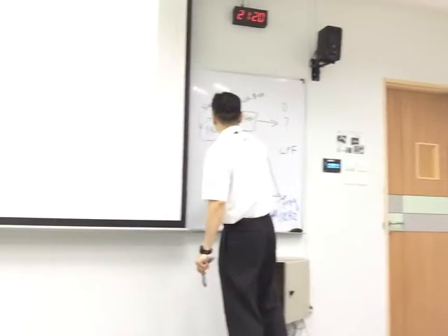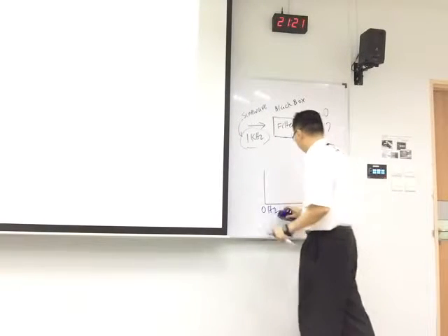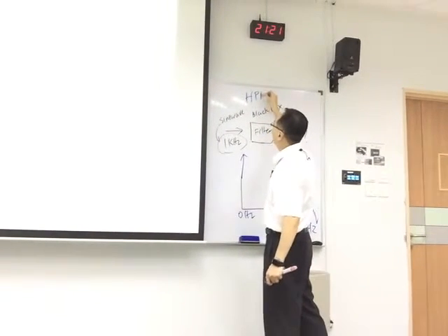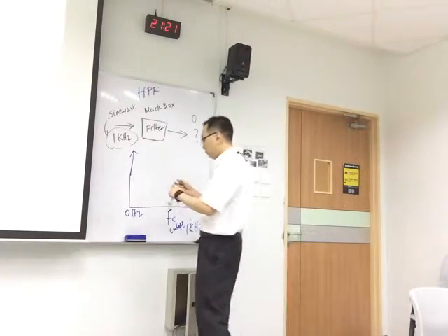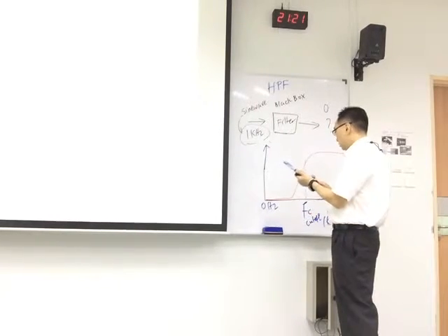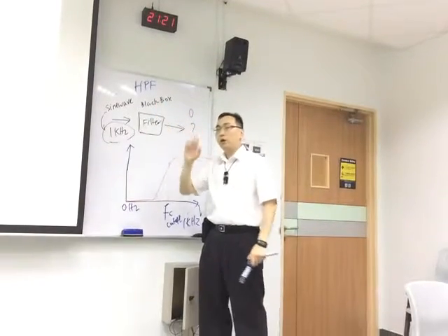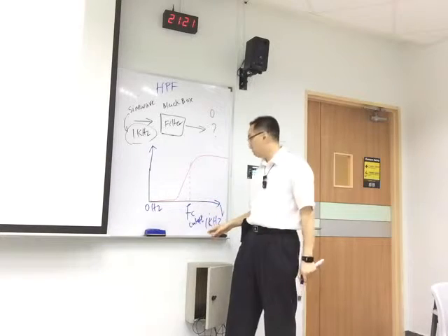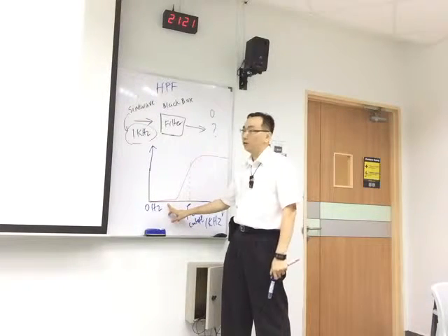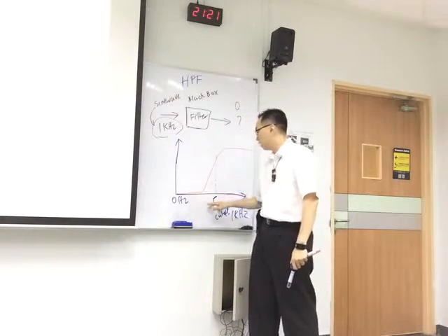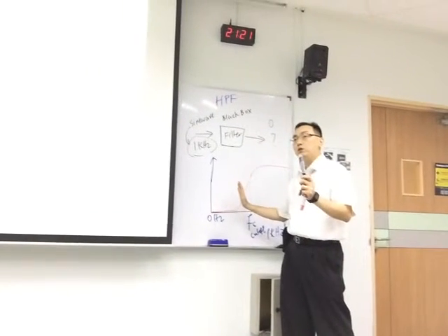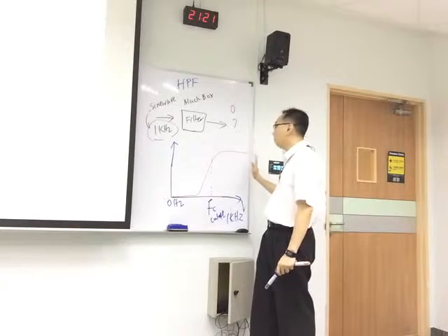One final one before we end the evening is the high pass. We will do the band pass in the next lesson. Now for high pass filter, HPF short form, what does it do? The profile looks like this. It has a certain cutoff as well. For the high pass filter, the cutoff frequency may be, let's give the same example, 1 kHz. It means that if I'm at 50 Hz, can the signal pass through? No, very obvious. Anything between 0 to the cutoff, this band here, is not allowed to pass through. So frequency above the FC will be allowed to pass through.